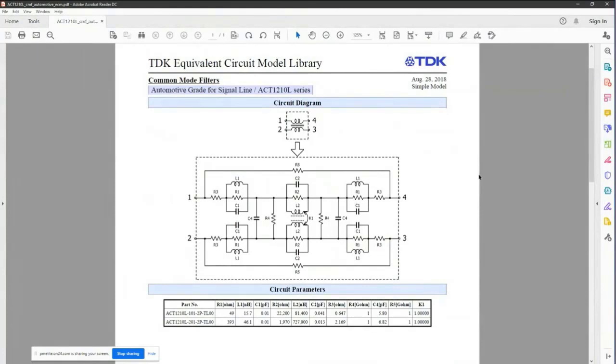If I buy a capacitor from a surface mount component vendor, it has inherently a parasitic series inductance and series resistance associated with it. It's important that those component parasitics be included in the analysis, because they can have big effects. That's why component vendors have so many different product families, because some are good for some applications, and for other applications, they're a bad mistake.